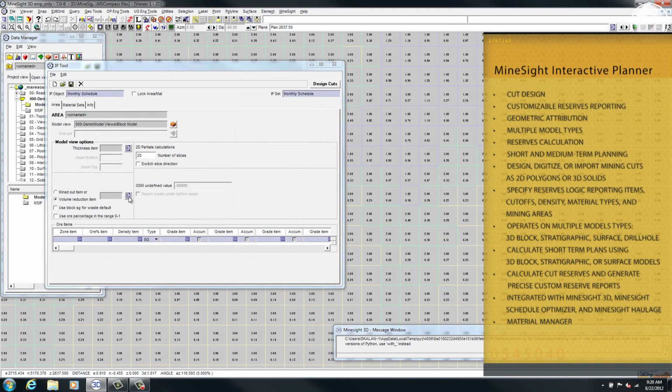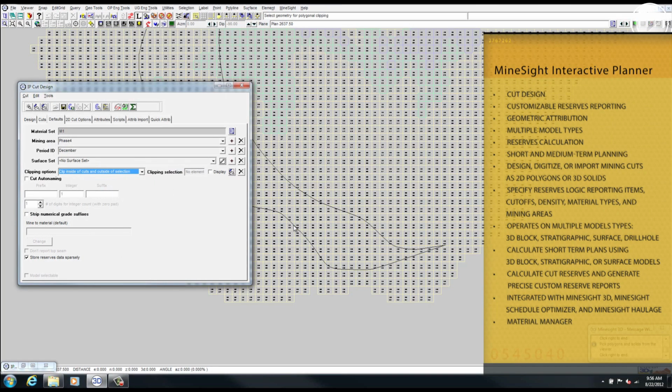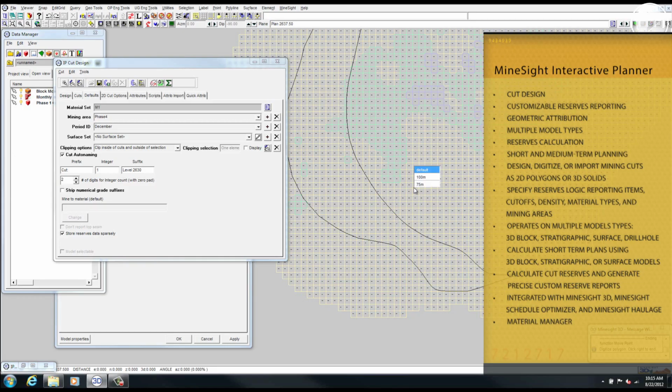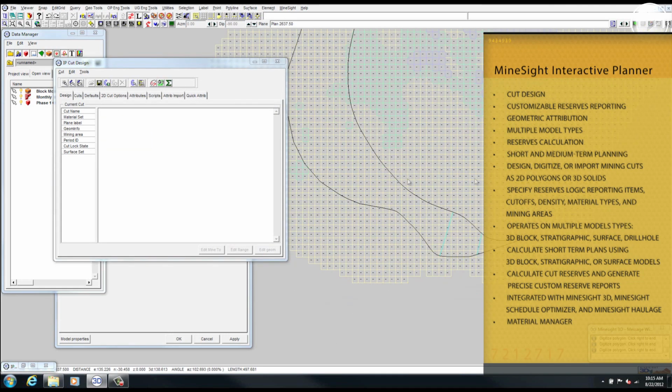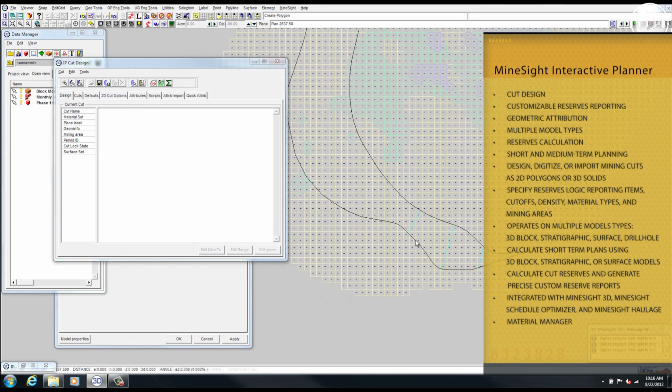When creating a short-range plan, we have to make sure that we have the correct amount of ore and grade going through the mill to meet budget. So I'm constantly watching the grades and making sure that we're achieving the grades required for the budget. My main use of MineSight is the interactive planner. It allows me to take cuts of where they're mining and get grades and tonnages immediately. And then I can compare that to the mill to make sure we're on target.